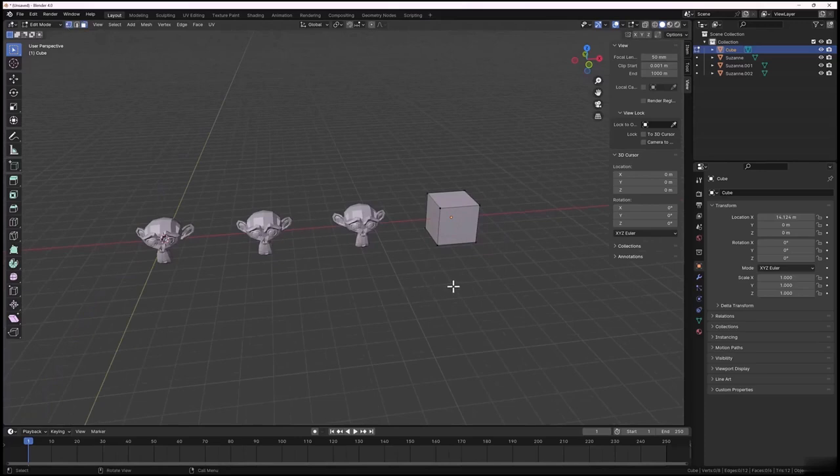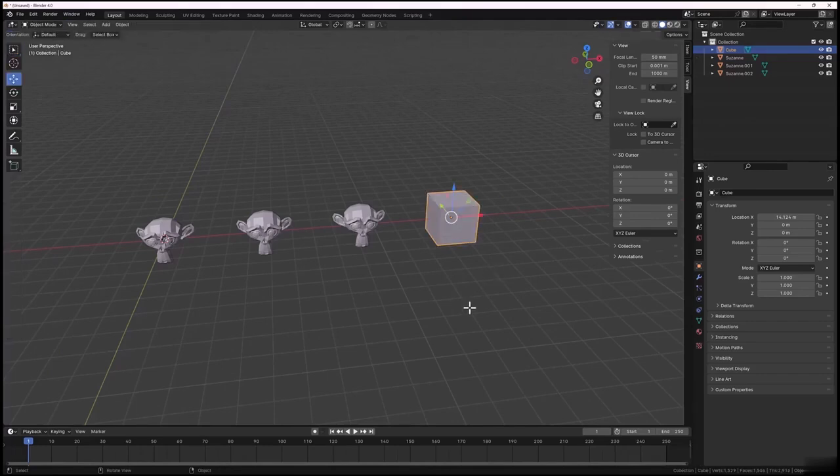All I really want to demonstrate is the simplicity of the mesh on that cube. It's as simple as it can get right now. So let's hit the tab button to go out of edit mode back into object mode. Let's select the cube again and go over to the spanner, which is the modifiers.